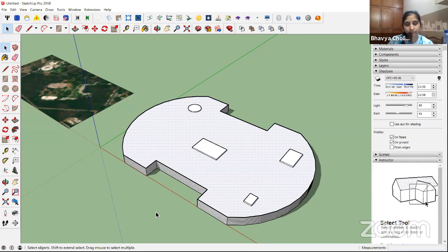But according to SketchUp, they consider the shortest day as December 21st. So for this software application, we will take December 21st as well as June 21st into the criteria. So we will consider the shortest and longest days to perform the shadow analysis for our project for the time being.